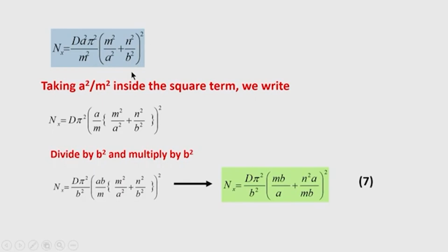This term can be arranged in such a way that we can get a clear-cut idea at what half wave number or what aspect ratio the buckling takes place. The boundary condition is simply supported along all edges, and you should mind that if the boundary condition is changed, the buckling load is also changed, that is, the solution of the differential equation will be different.